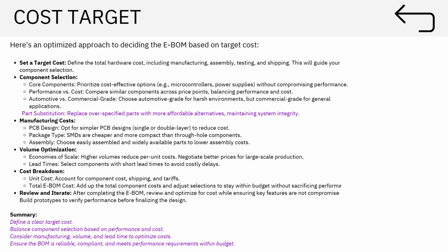Again you have to re-release the PCB Gerber. The PCB will come, then you populate, and then you test. So we are talking about close to 4 to 5 weeks of cycle, because it takes time to get the PCB fabrication done, and then the PCBA part. So it becomes very critical. Whatever you are doing, make sure you are checking it thoroughly. What I suggest is to get the schematic reviewed by your peers or someone who has a better understanding, if you are just starting something on your own.